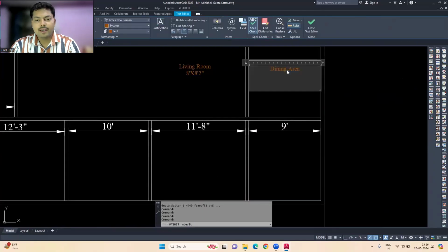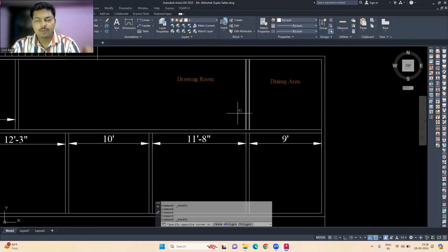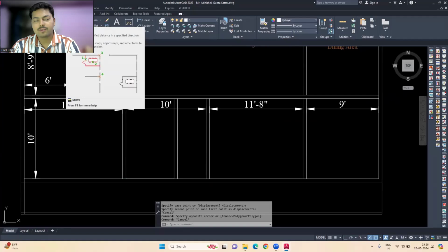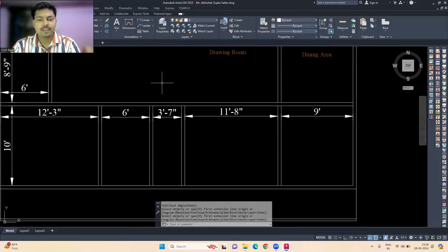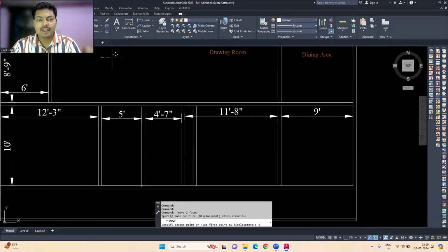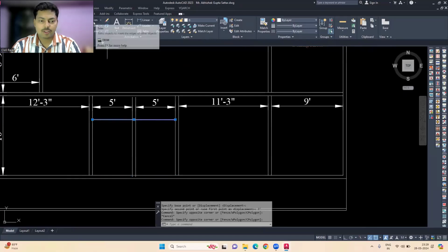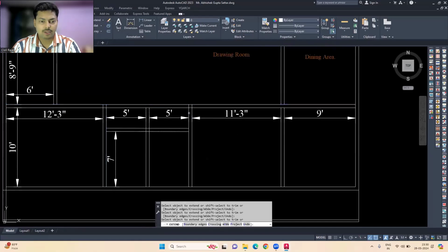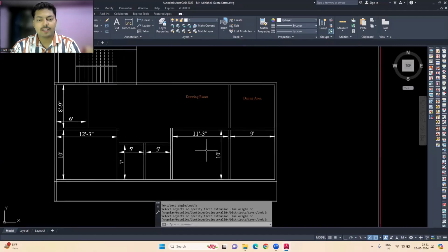Now over here at the, you can say, the northeast portion, I am just placing the dining area over here because that is the best place. However, according to the vastu, the puja room should be placed over there, but I am planning to keep the kitchen in the southeast corner, and the dining area should be as close to the kitchen as possible. So I am keeping it over there. Here I will place the toilets. Okay, so one toilet I will attach with the bedroom and another one I will keep common.